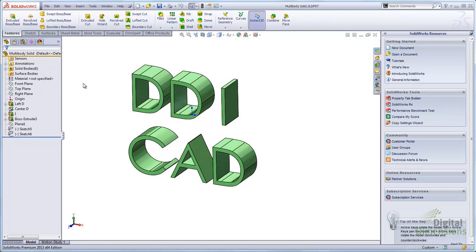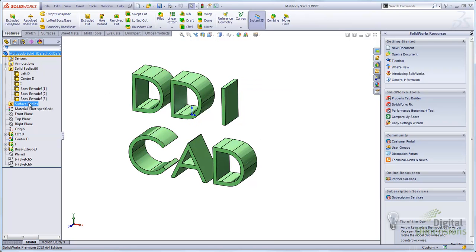This is a first example, just a real simple example. Now when I select one of these bodies here, you can see first off I have 6 bodies. So when I select them now it doesn't just show the feature, it shows the highlight of the actual body in the solid body folder. Again, it works with surface bodies and the cut list items. So you can see it picks the right one.